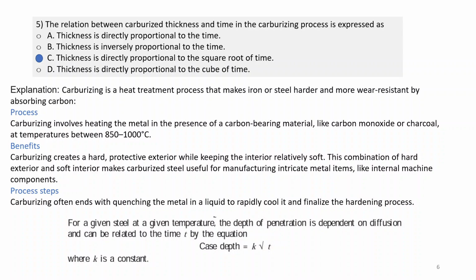And for a given steel at a given temperature, the depth of penetration is dependent on diffusion and can be related to the time T by this equation. Here depth equals K times root T, where K is constant and T is time.